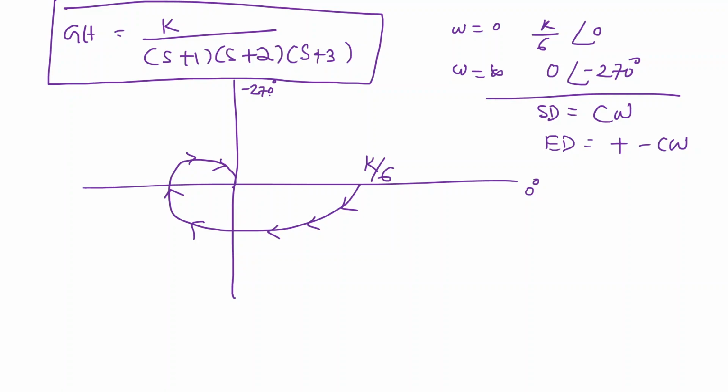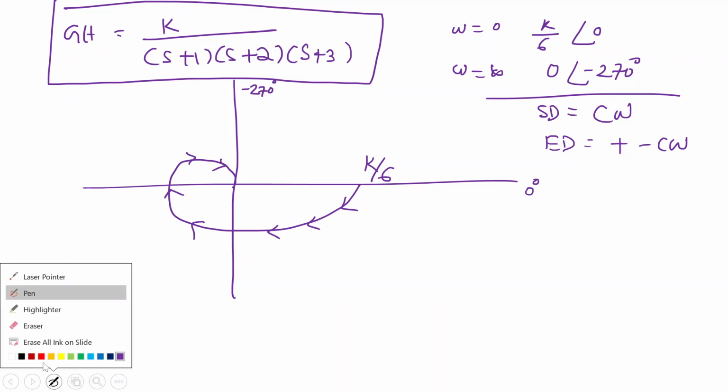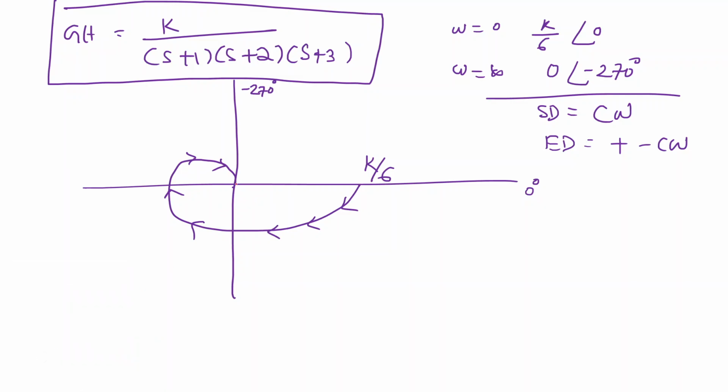Is it clear? Yes, sir. This is the polar plot, simply. Now, first, second, you have to take the mirror image because the Nyquist plot will be drawn that way. So now I am taking the mirror image. If I draw the mirror image, it will be something like this, and it will come to here. Mirror image up, right? Okay, yes, sir. Just 0 degree. You don't change the direction, sir. Whichever path you are moving, one path you have to move.